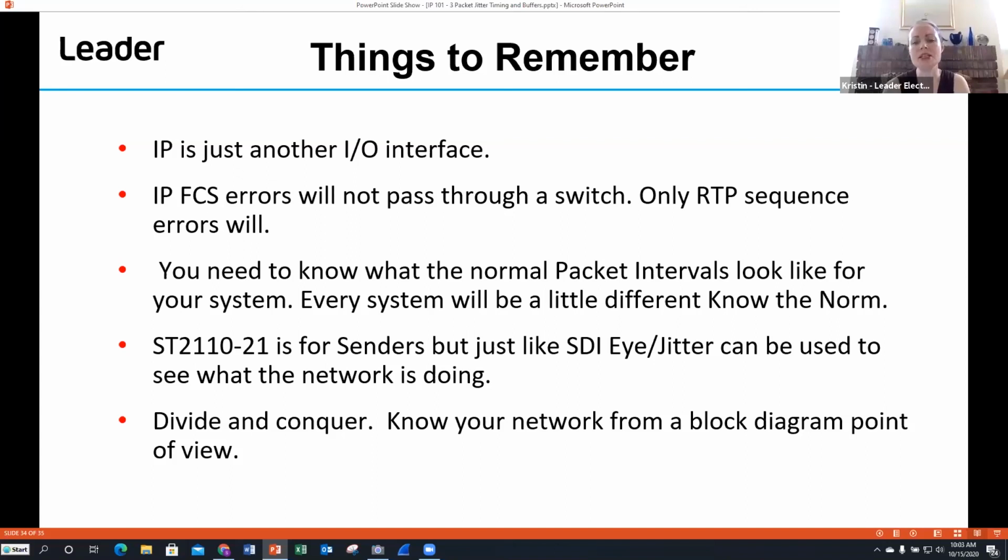What PTP reference generator or source are you using, and how does it lock to BB? So I am using the Leader LT4610. The beautiful thing about it is it's GPS locked, and it generates black burst. So it is my source of black burst. It is my source of PTP. Since they both come off the same GPS, they are absolutely locked to each other since they're coming out of the same sync source.